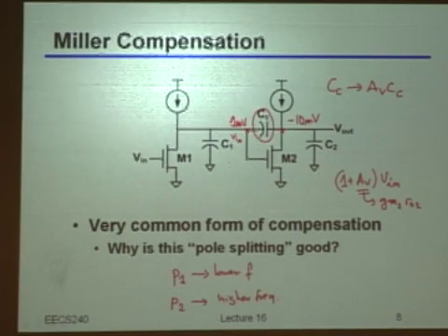What's the story with the high frequency pole? Why do I shift it to higher frequencies? Do you have any clue on that? So do you remember where the spot of the second pole was at the very beginning? It was -1 over C2 R2. What's going on here? Why did I shift it to higher frequency? Any hint? Any thought?